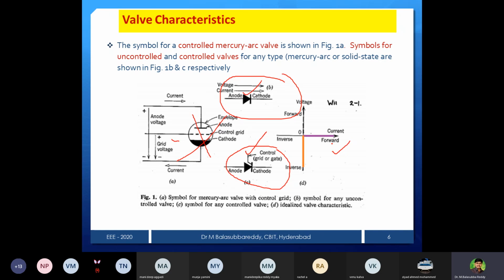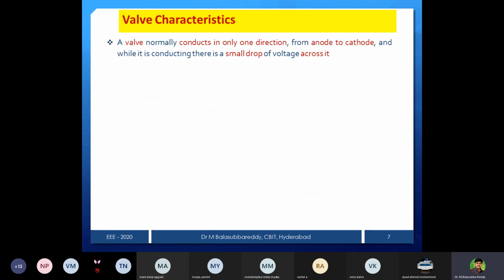So you can simply identify the switching on and switching off instants of the device. When the switch is on, the voltage across the device is 0, or preferably very negligible. Under ideal conditions we can say straight away it is 0. Similarly, when the switch is open, the voltage across the device will be the source voltage. That way we can easily identify the characteristics of a switch.